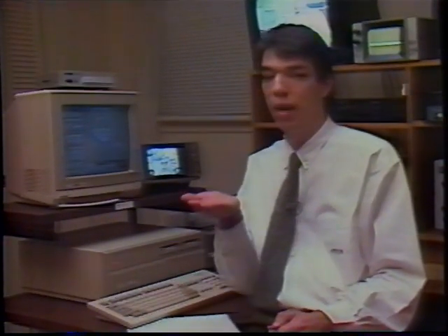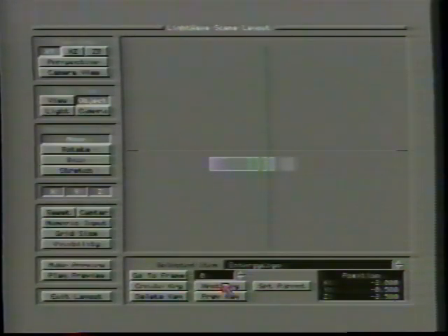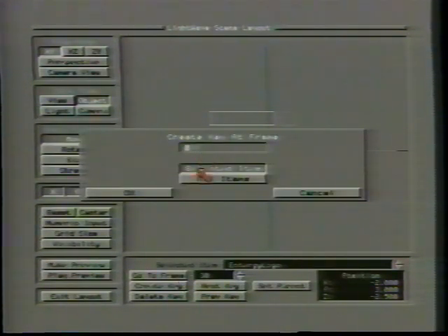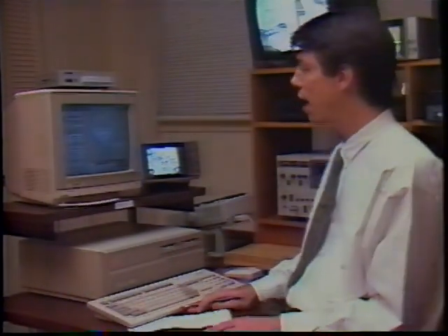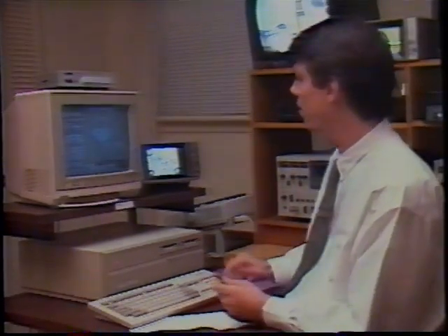I didn't quite like the effect that this has. It's almost what I want, but not quite, because the object comes out of the water and spins in one even motion. What I'm going to do is break it down. I'm going to give it 1 second to come completely out of the water, and then 3 seconds to turn to the audience. Fortunately, with Lightwave, that's real easy to do. All we're going to do is position our object right above the water and set a keyframe at frame 30 and let it figure out the rest. Okay, we're going to do that now, and we'll come back to you with a wireframe animation of that when it's done cooking.